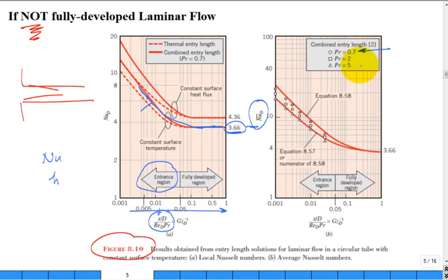When you see Prandtl equal to 0.7, what does it make you think of? Come on, you've solved enough problems. What type of fluid has a Prandtl number of 0.7? All right, slow down, take a deep breath, hint, deep breath. All right, you got the hint, air. Ideal gases, around 0.7. If you're up in this range of Prandtl numbers, what type of fluid do you think that is? Water, liquids. Yeah, like water. Water has a temperature dependent Prandtl number.